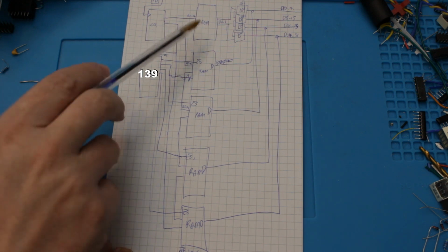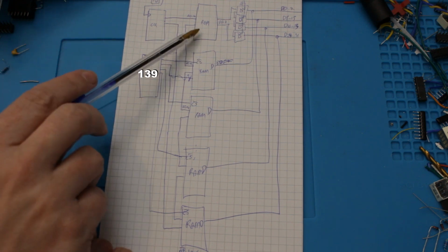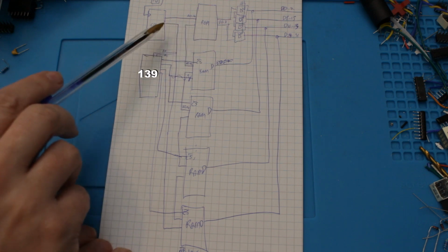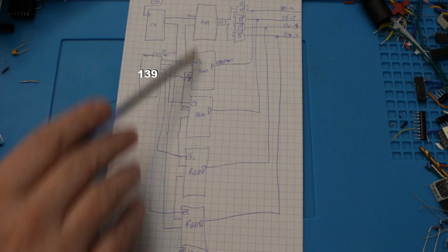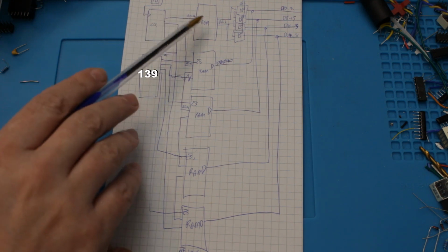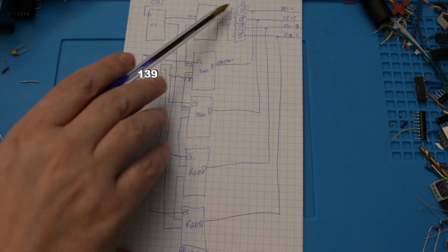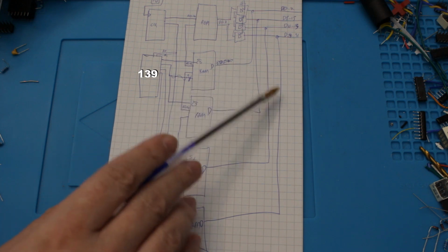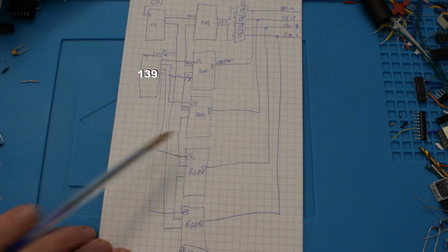I haven't really drawn on the diagram how that would work, but what I was particularly thinking about here was having a system where the ROM is actually never directly connected to the CPU. Rather than connecting the ROM to the CPU, on startup, before we even start the ARM, we run this counter through the entire address space of the ROM, and we essentially drive the bus from the counter with the ROM outputting its current data here, bus transceivers here making that data go through to the individual parts of the data bus, so that just replicates the ROM's 8 bits of output across the 32-bit data bus.